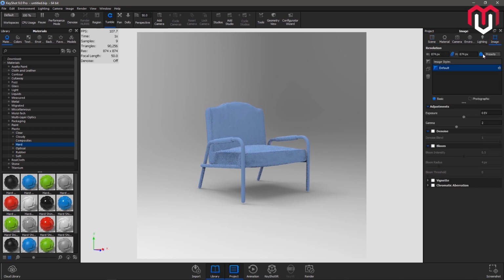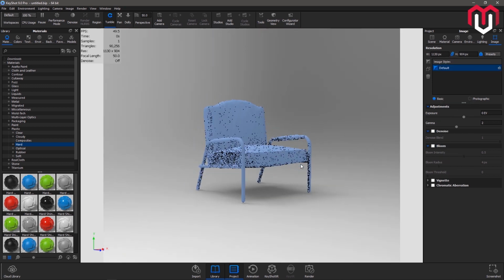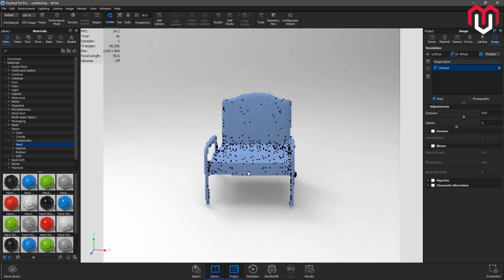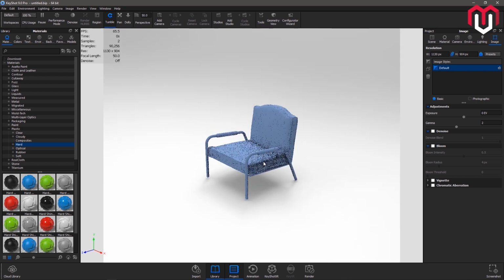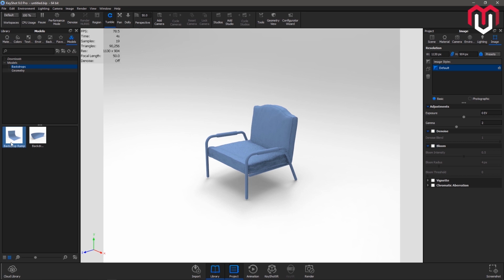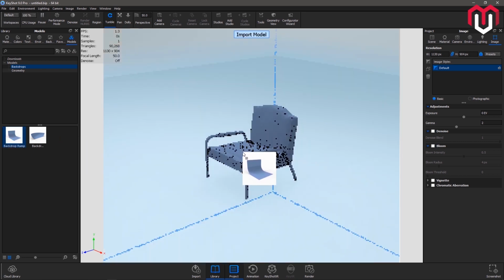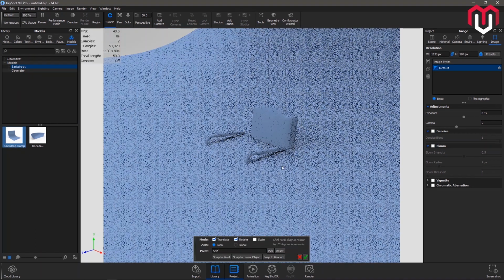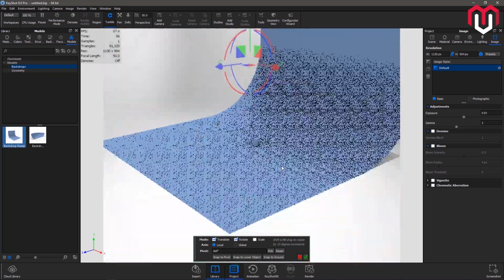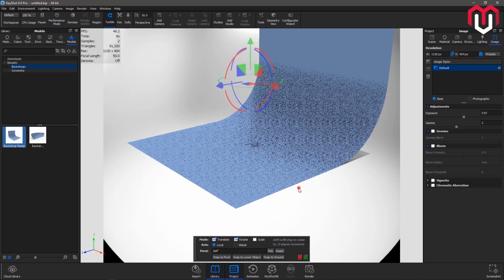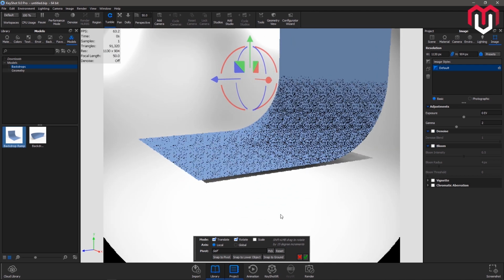At first I am going to change my view size here, which is okay, this is fine. The next thing is to add the backdrop. You can find the backdrop in models and just drop it on the chair, and it will create the model for you. Now just zoom out using the scroll button, and you can see it's pretty large.